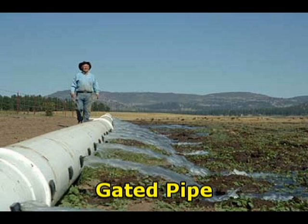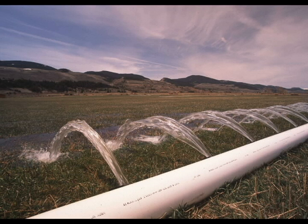Gated pipe. Gated pipe is made of lightweight metal or plastic and has small gates or openings spaced to match the furrows. The pipe comes in sections that are easy for one person to handle and is fitted with simple watertight connections. A slightly different product made of vinyl-coated glass, cloth, butyl, plastic, or canvas hose and equipped with small outlets can be used for the same purpose.